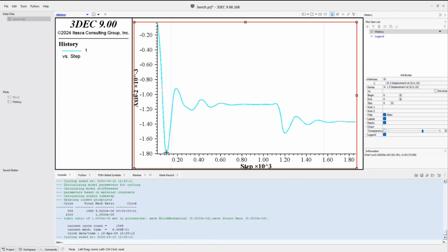There's initial downward movement because, again, we turn on that gravity and there's a big downward push. It bounces around a little bit, comes to some equilibrium. This is everything elastic. Then it turns everything to its true strength, and you get some more downward movement. So presumably something in here failed. If nothing failed, nothing would happen. Some zone somewhere failed. There was some stress redistribution. We end up with a little bit more displacement than we had to start with.